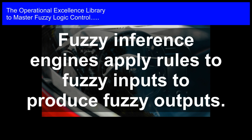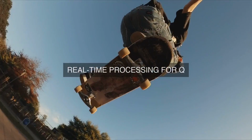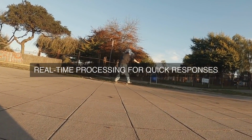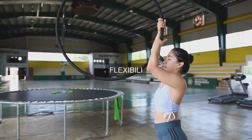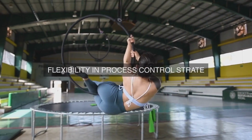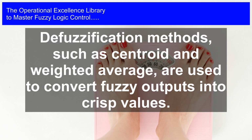For example, in a pressure control system, the membership function can be used to represent the degree to which the pressure is high or low. Thirdly, fuzzy logic control uses fuzzy rules, which are if-then statements that relate the input variables to the output variables. Fuzzy rules are used to encode the expert knowledge and experience of the system designer, and they provide a framework for reasoning about the uncertainty and ambiguity in the process data.